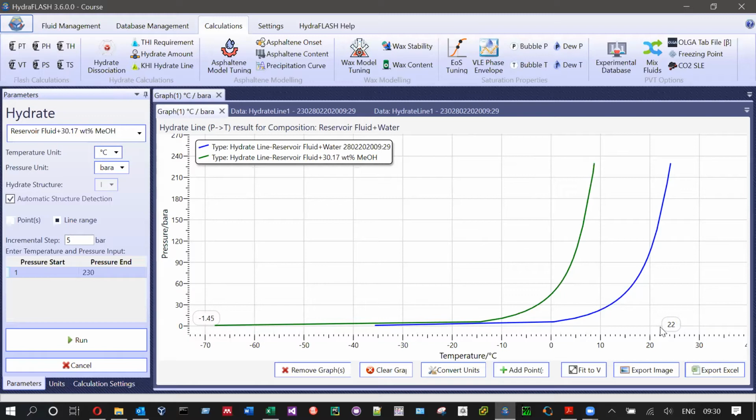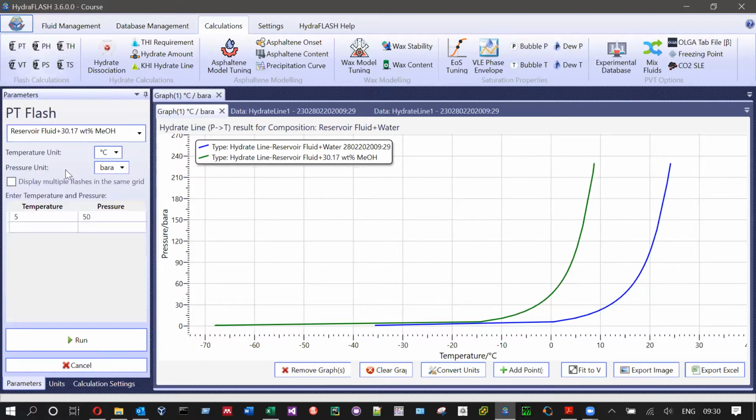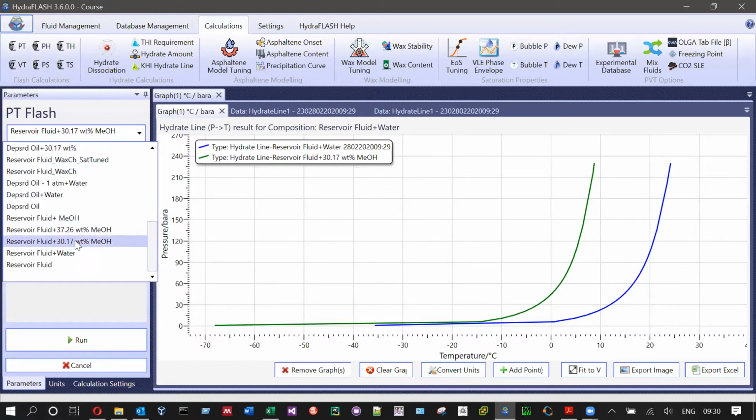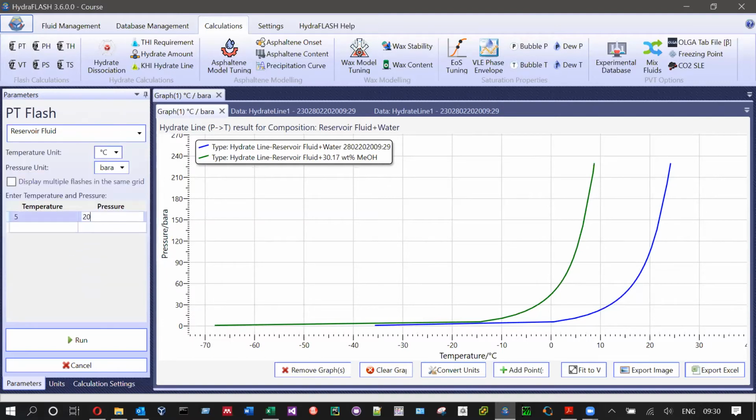That is the pressure on the surface, and then we take into account the hydrostatic head. So that will be the maximum pressure of the pipeline. We know the temperature of the pipeline, so together we can calculate the new operating condition in the pipeline.